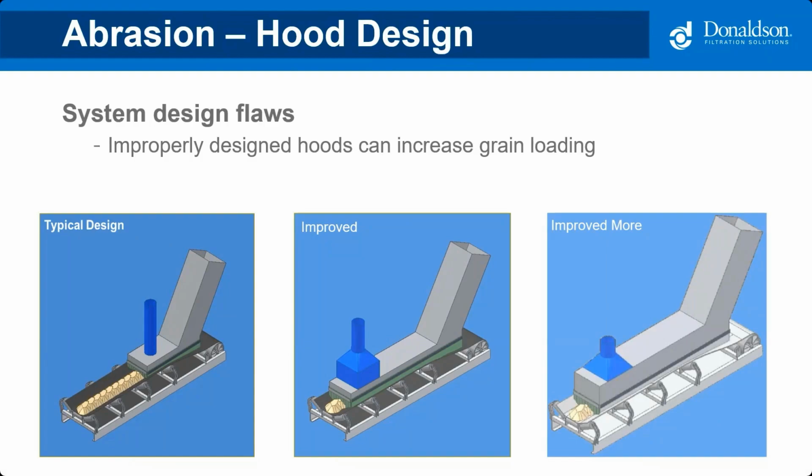Well, what happens is that the capture velocity of that duct, because it's right above the product, is going to be really high. And you're actually going to be sucking a lot more than just the nuisance dust. You're going to be sucking up a lot of sand. And then all that sand is going to end up just beating the heck out of your bags and ductwork along the way. So the middle and the right-hand pictures are just a couple of ideas for you.